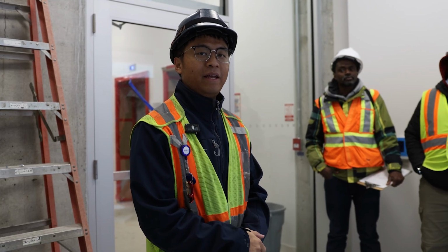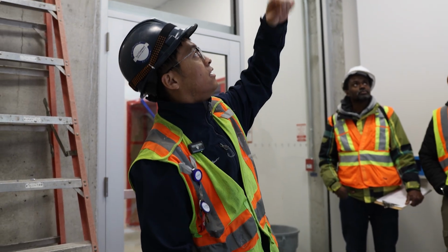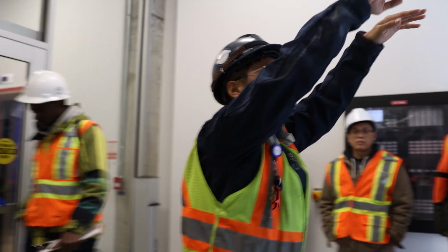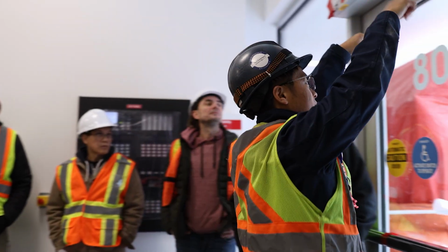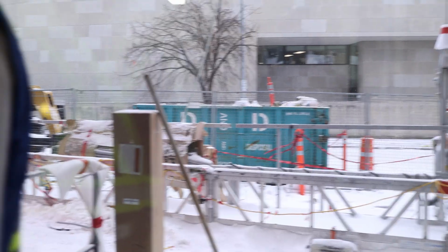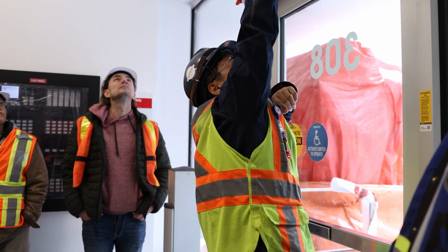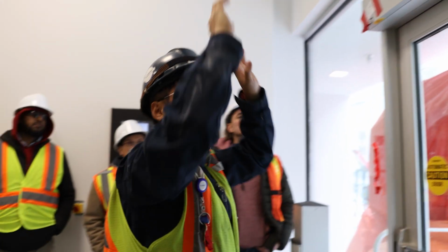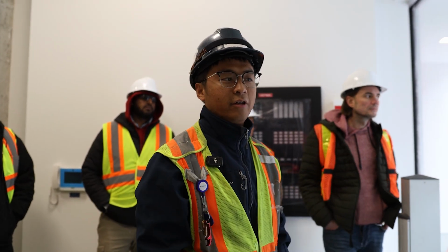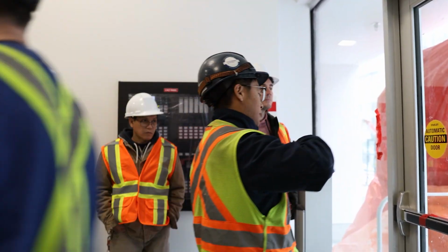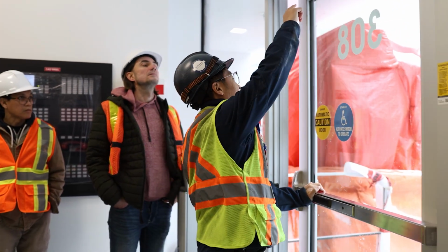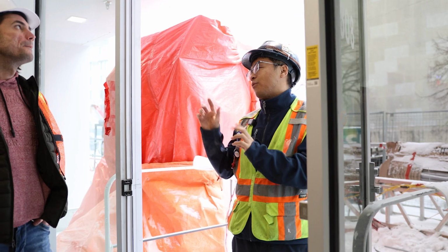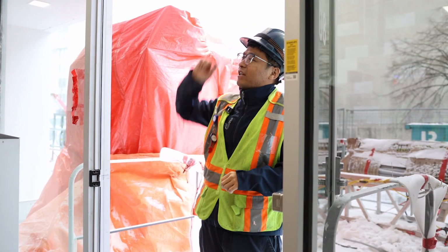We also have EMA number 6. The unit is above the ceiling right here, but it actually serves the soffit area outside. If you are looking for the thermostat, it's right above us, above the door. If you pop off that ceiling tile, you will see a thermostat. That's the space temperature we are monitoring. It's an electric makeup air unit, number 6. Same idea with EMA 1, 2, 3, 4. It's just the location.